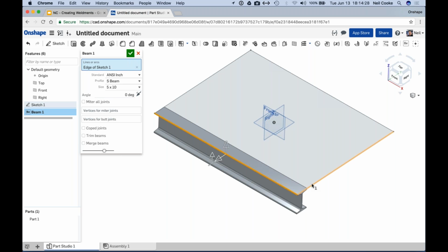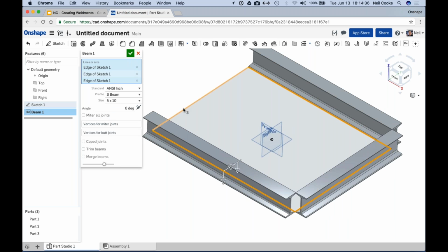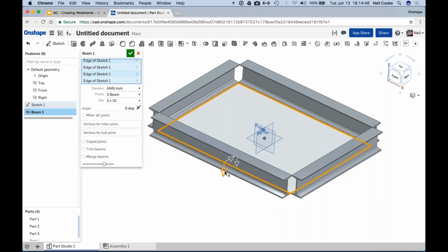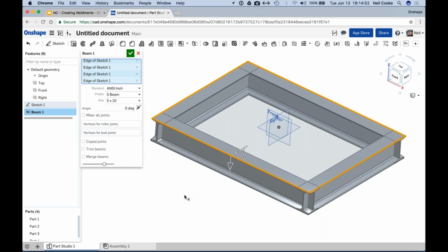Now, as you add more sketch entities in there, what you might find is that sometimes this might jump around, and the reason being is that again, I might have to come up with a slightly better algorithm to work that out, but it's basically basing it off the number or the type of face that you are selecting. So it's probably a good practice to build your frame or select what you're going to use first before you start modifying the position of the actual individual beams. Now once you have those, you'll see those in this case are overlapping.